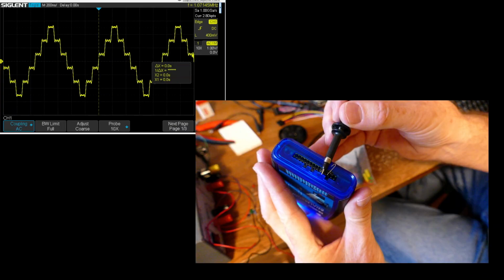Here's a bonus, a direct probe of a 1 megahertz stair step. I think the M2K signal generation flexibility really is outstanding. So what's the conclusion? I think the M2K scope and signal generation below 1 megahertz is great and fully usable, even with flying leads and breadboards. With sine waves, you can even push it to maybe 10 megahertz under these circumstances. Triangle waves, maybe up to 5. Square waves, you're probably better off stopping at 1 megahertz.